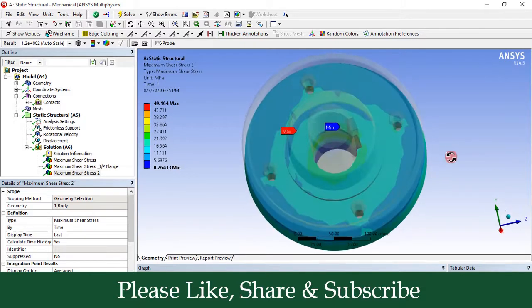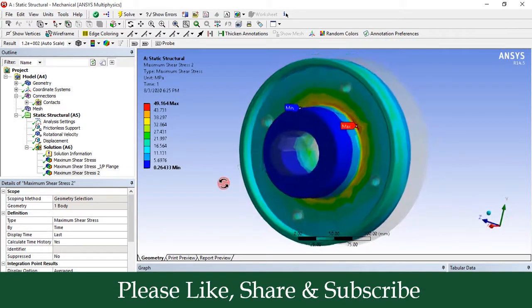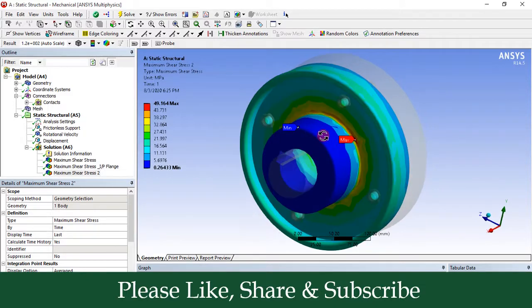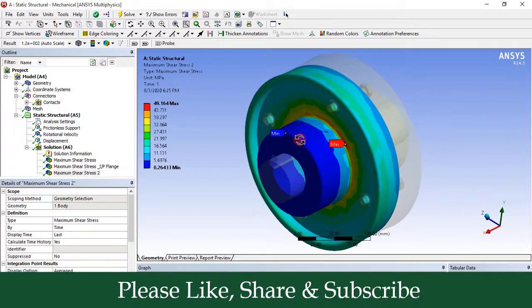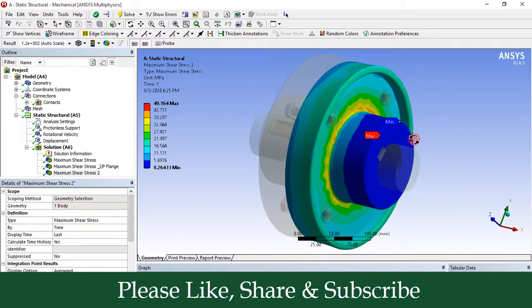So you can see here the maximum shear stress in the output flange. You can see here the value of maximum and minimum shear stress. So at this point, that is at the junction of this flange and hub, there is a maximum shear stress, and on the point of hub the shear stress is a minimum, that is at this point, and here the shear stress is maximum. So in this way we have checked the maximum shear stress for input flange and output flange.